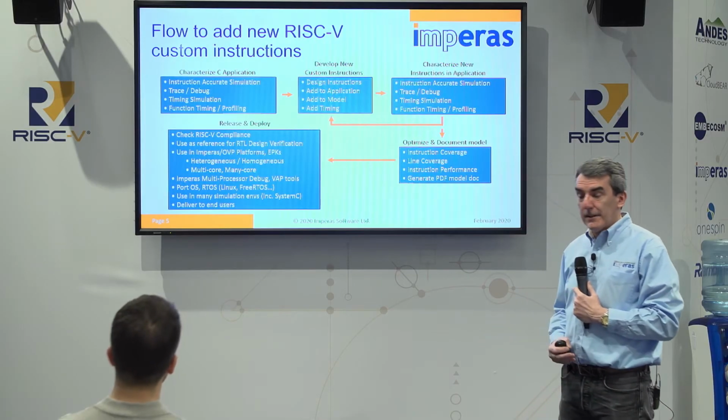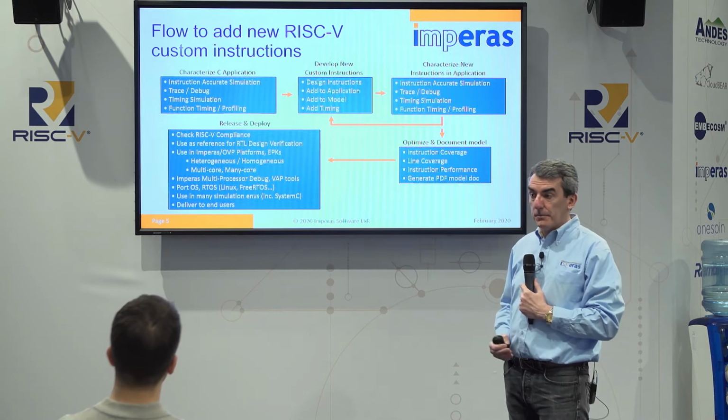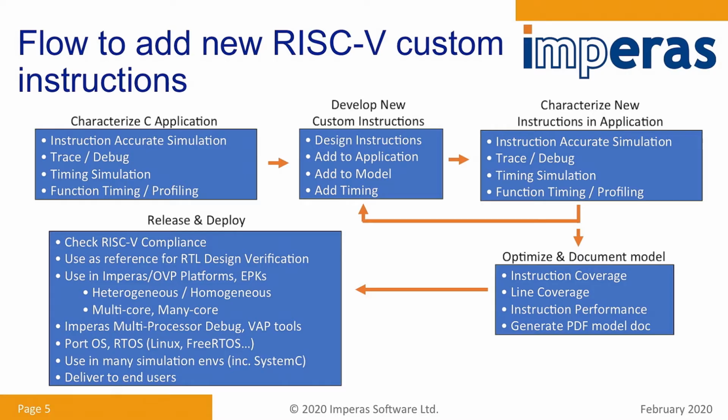As you want to add a custom instruction, we think a good place to start is your application software. You can take your full workload, your full OS, and your application, and profile your code, and look for hotspots and tight routines where a candidate instruction could help your application. We think the software is a great starting point to look at these custom instruction capabilities.